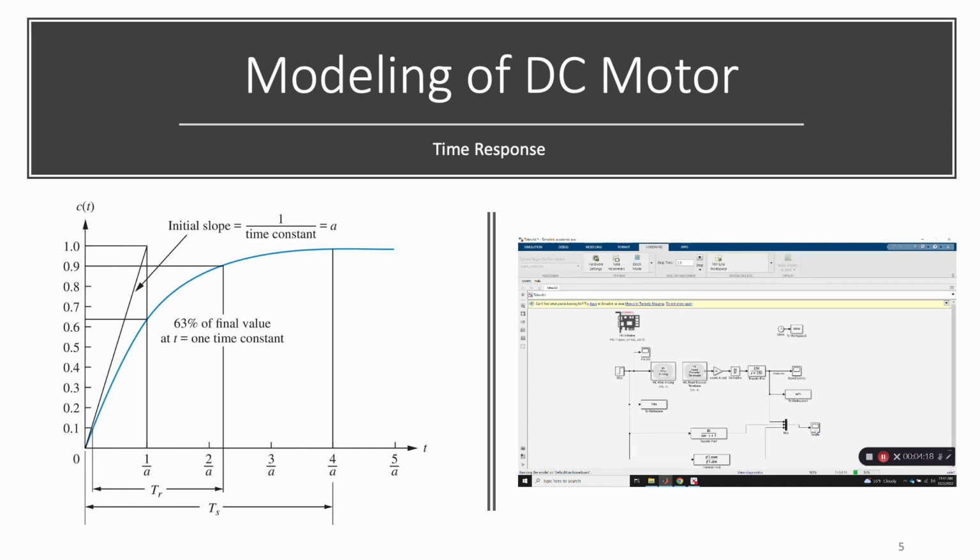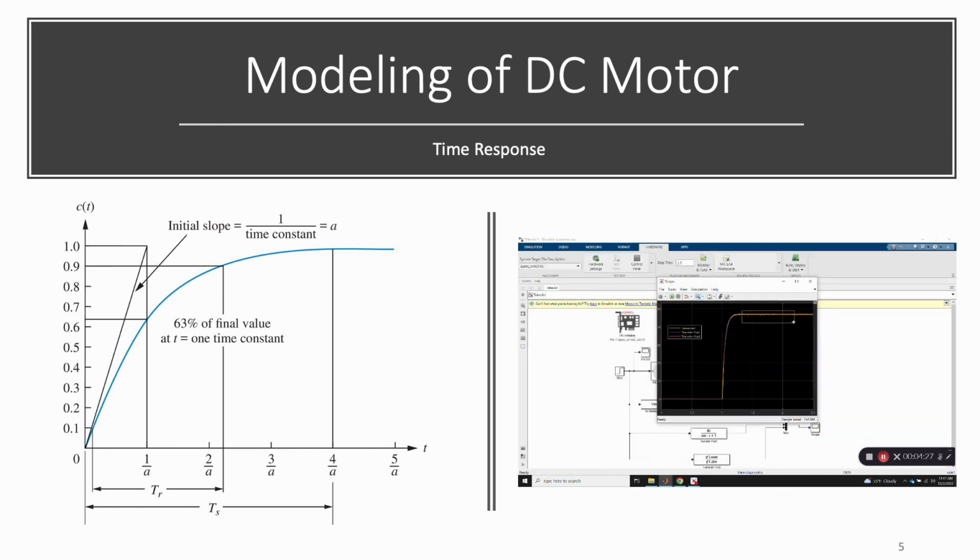So you're really looking for a high fit, like 95%, 96% fit. And you can now include the second transfer function from the system identification to be able to compare the experimental data, the transfer function from theory, and the transfer function from system identification.